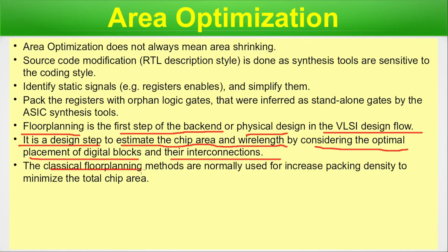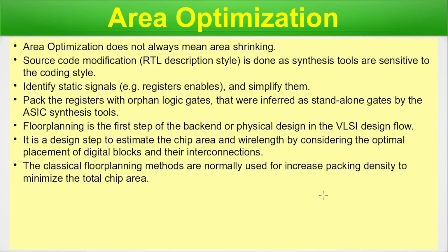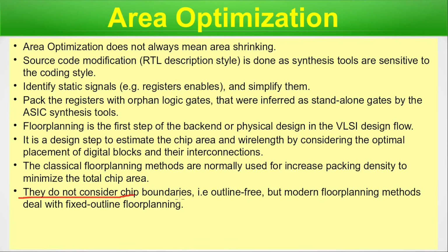Next, we have the classical floor planning methods that are normally used to increase packing density and minimize the total chip area. There are some classical methods, and there are some advanced methods nowadays which are used for the packing density to be optimized, and that should minimize as much as possible, obviously, the chip area. They do not consider the chip boundaries, that is the outline, but modern floor planning methods deal with fixed outline floor planning. These are methodology things that you will find in your company or in future whatever company you will join, assuming that right now you are a graduate.